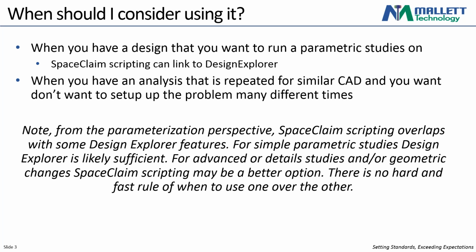from the parameterization perspective, SpaceClaim does overlap some with Design Explorer in terms of its features, and it can actually work with Design Explorer, where you can specify parameters that are script parameters and have it interact with Design Explorer, varying those as well. So generally, I would look at Design Explorer for relatively straightforward and simple parameterization studies, and then I might switch over to SpaceClaim scripting for more advanced and global studies where you're changing many different things, trying to maintain connectivity well, and potentially not having super consistent geometry for different problems.